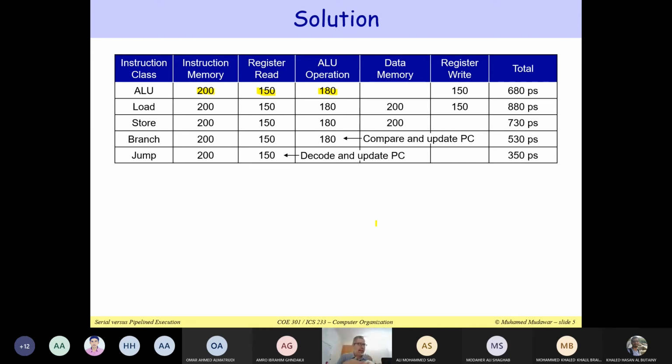For example, if you have an addition with a slow ripple carry adder, that might increase the delay inside the ALU to compute all the bits of the sum. Subtraction can be done as addition with the 2's complement. So you look inside the ALU and you look at the longest delay.